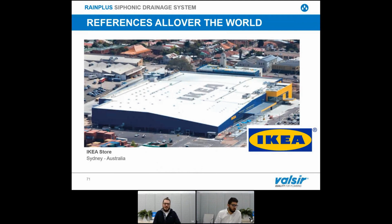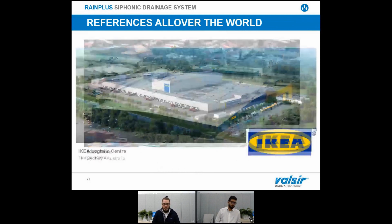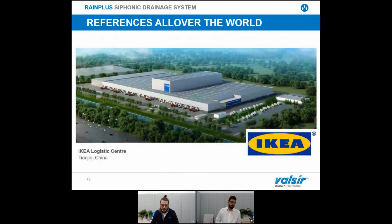But you can understand the difficulties of this type of building because it's really wide. So you have to drain the water from the middle. And the Siphonic system is the best solution and application for this type of building because you can ensure that you can drain the water in the middle of the roof surface without having to create a lot of slope. Also this IKEA in China, which is not a factory but a logistics center with a really large surface.